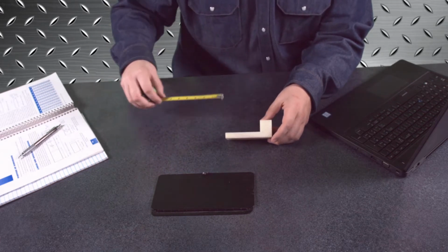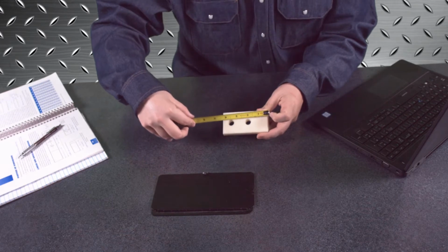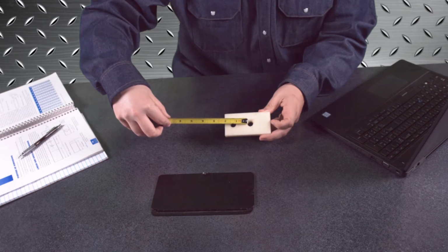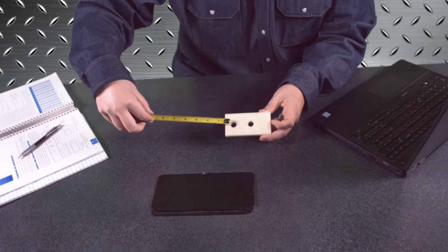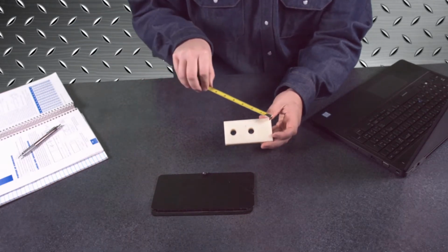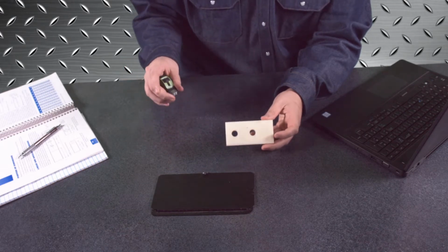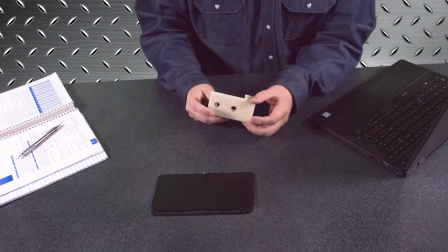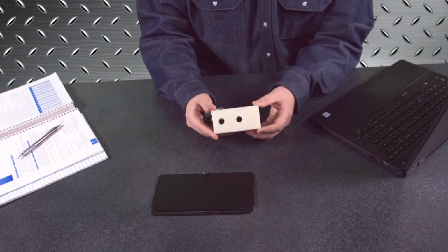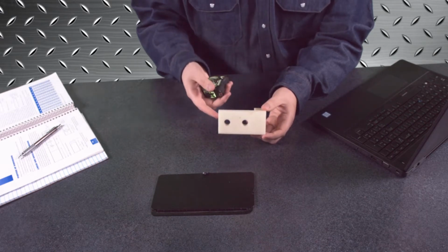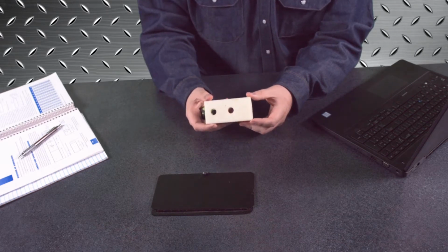If you were to measure across this part, or if you were to be measuring these holes across, it would measure from here to this part of the hole, then from this side of the hole to this side of the hole, then from here to here, then from here to here, and then here to here. That'd be conventional dimensioning, and you'd have a measurement for each one, and you'd have an overall length. With conventional dimensioning, you are using fractional inches whenever they call out the sizes. So it'd be 1, 1 1/4, 1 1/2, whenever they'd give you those measurements.